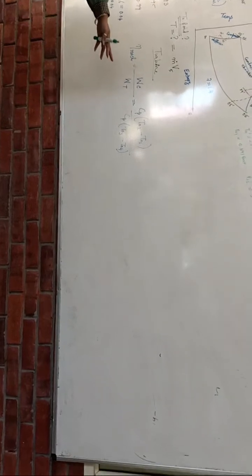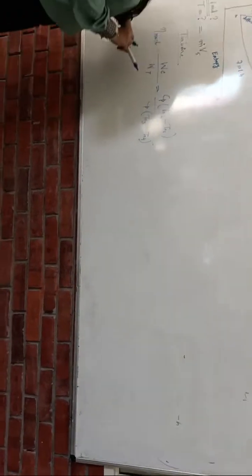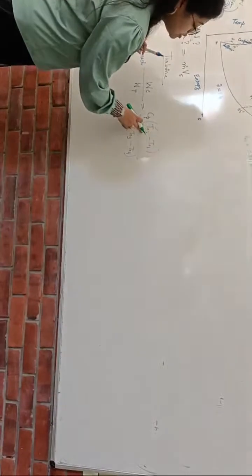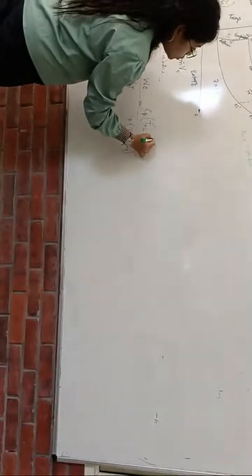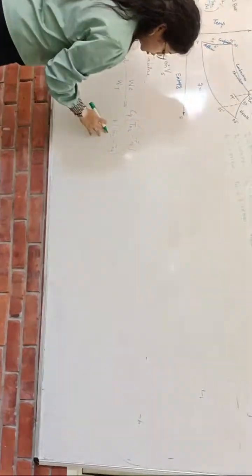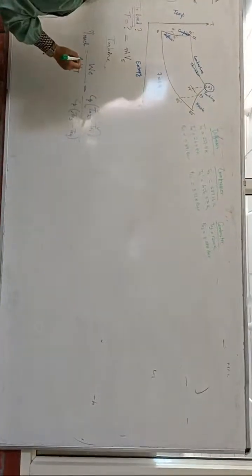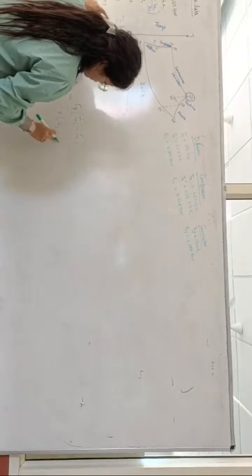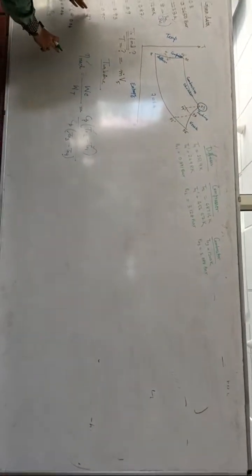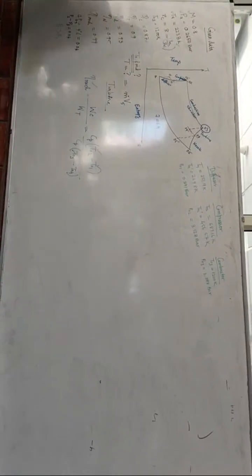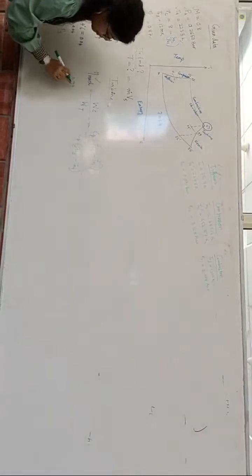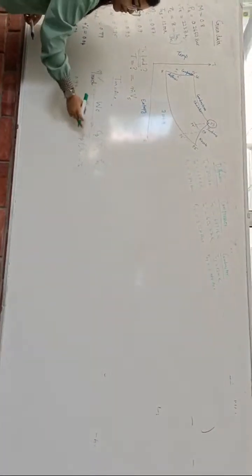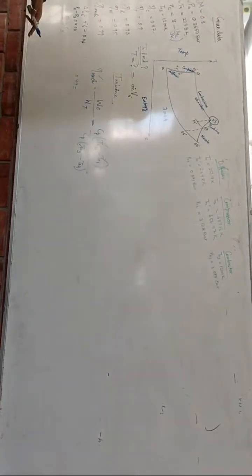Fine. Now here, do you know the values? P03 and P02 are known from here. T01 is known from here. T03 is given in the data as well as over there. P04 is unknown. Mechanical efficiency is also given in the problem, so now it's very easy to solve the unknown: 0.99. Now the Cp value is not given in the problem.